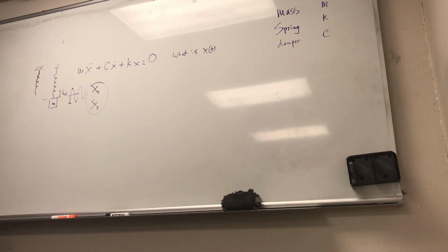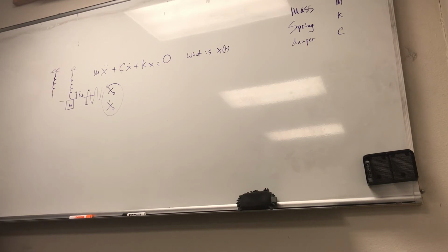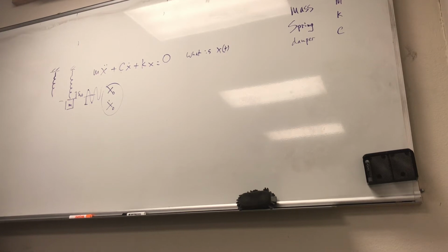Okay, what if it's 2 degrees of freedom? Well, this is fairly clear, the one on the left in A. You have two masses. I cannot just say it's x1. If x1 is fixed, x2 could be anything, right? So it's not well defined. I have to also define x2. That means I need two pieces of information to describe that system, and hence we call it a 2 degree of freedom system. Likewise here you have two disks, and each one is rotating independently. So I need theta 1 for this one and theta 2 for this one in order to figure out the exact situation. And how about this one? Why is it 2?